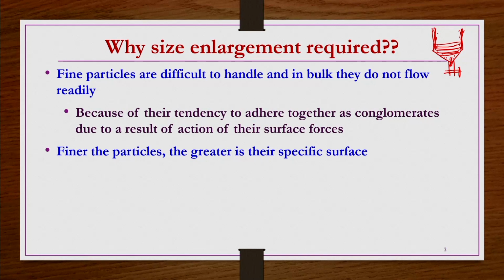Further, the finer the particles, the greater is the specific surface of the particle. If the specific surface is large, meaning a very small diameter particle, then in general it will take a long time to settle down, because the gravitational force acting on that particle is very small.